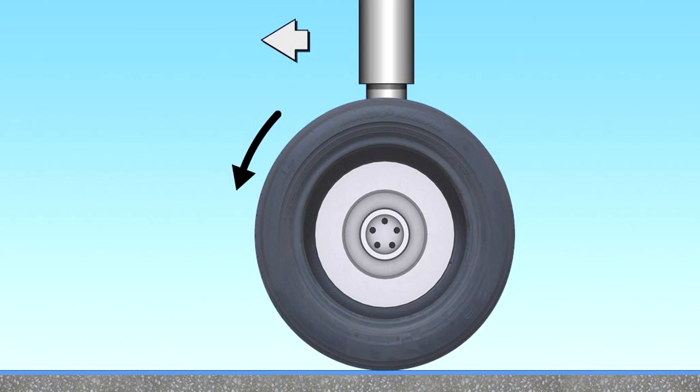The second type of hydroplaning is called viscous hydroplaning. It occurs because of the viscous properties of water acting like a lubricant. A thin film of fluid not more than 1/1000th of an inch deep cannot be penetrated by the tyre in the footprint area, and the tyre rolls on top of the film. Viscous hydroplaning can occur at a much lower speed than dynamic hydroplaning, but it requires a smooth surface.